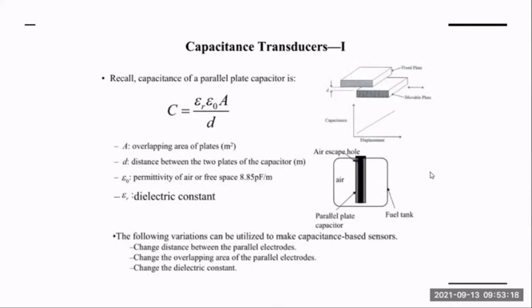So this is usually the use of capacitance transducers. Nowadays, most smartphones are using a capacitive touchscreen. Same principle: our fingers introduce a different dielectric on the two plates, so we are causing a change in capacitance. When the screen detects a change in capacitance, meaning there is an input, a touch, there is a command that is supposed to be followed.